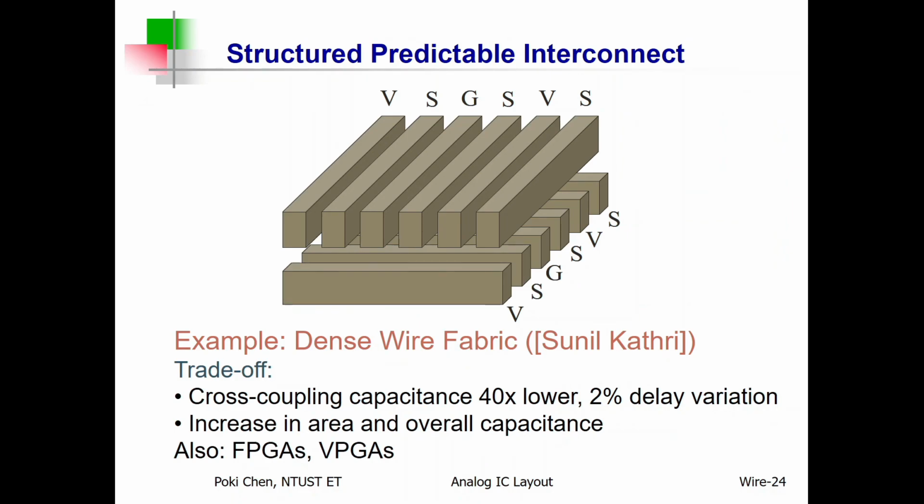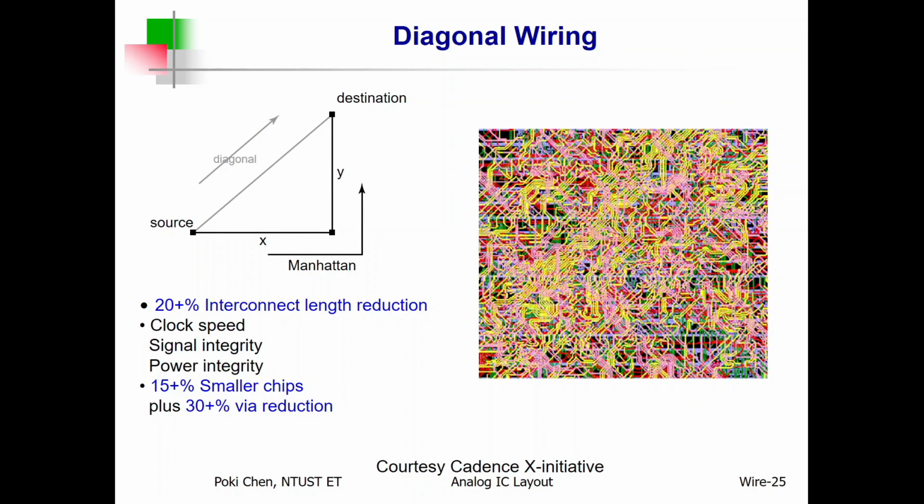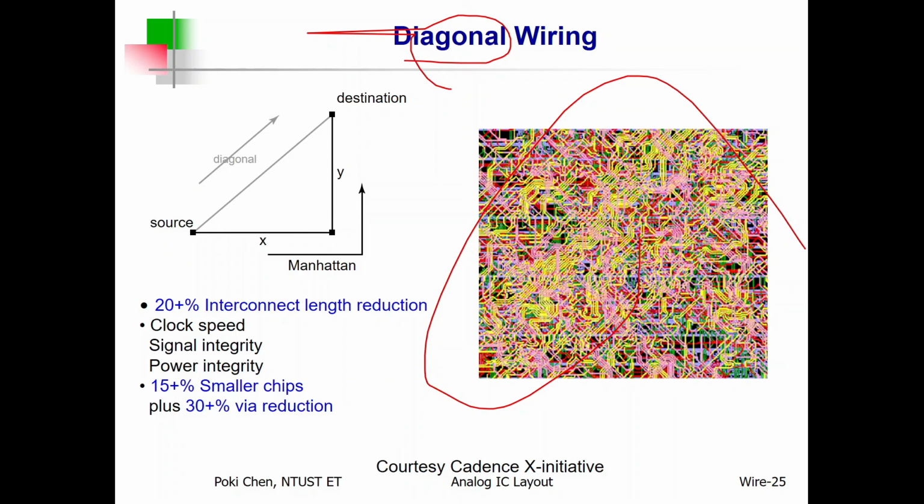Again, this is some kind of three-dimensional view. I think I told you already. Usually we do layout for such wires orthogonally, with horizontal lines and vertical lines. But if you can accept wiring along the diagonal axis, just like this, in practice, EDA tools can help you to reduce the layout area for the same interconnects.